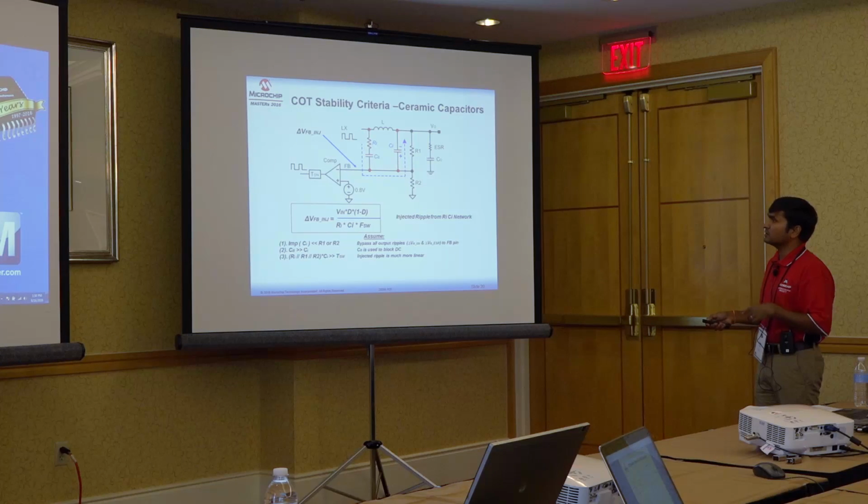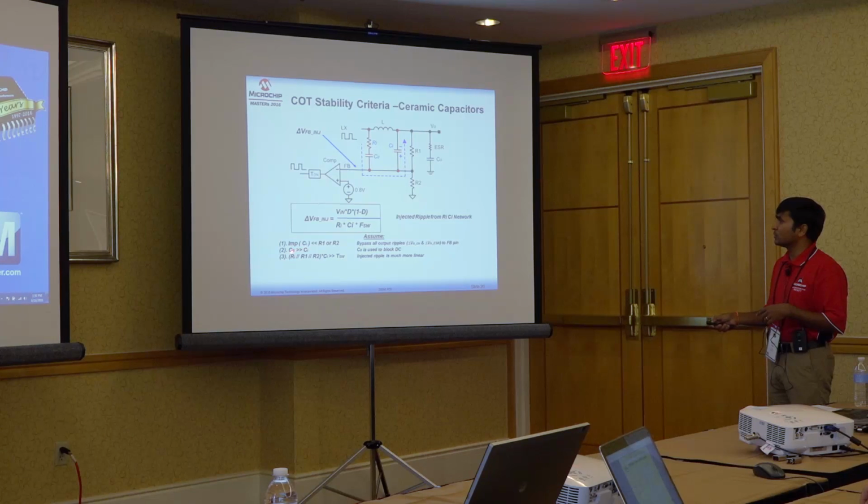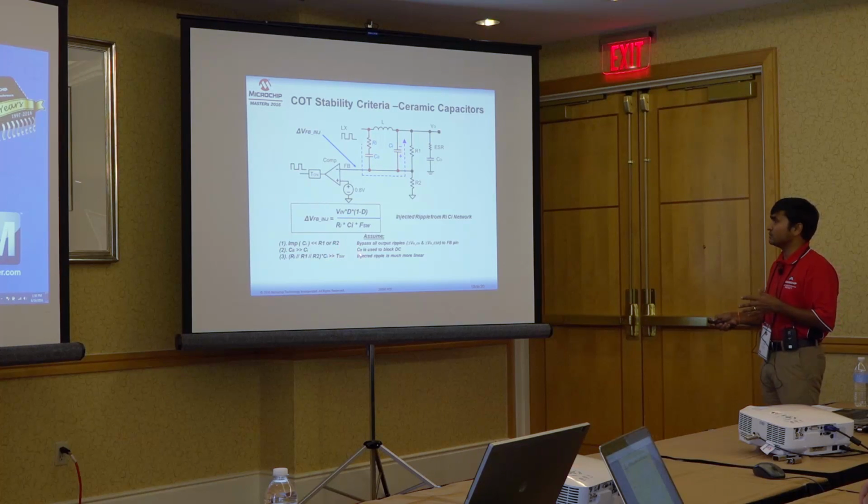The other thing we ask you to make sure is that the time constant provided by the feedback network impedance is greater than the switching period, because we want a triangular waveform at the feedback node. That is why we ask you to satisfy this equation.